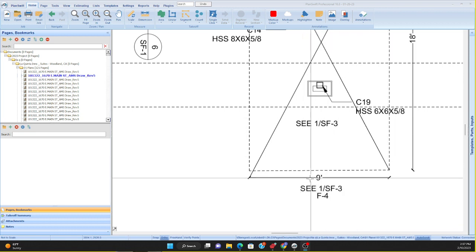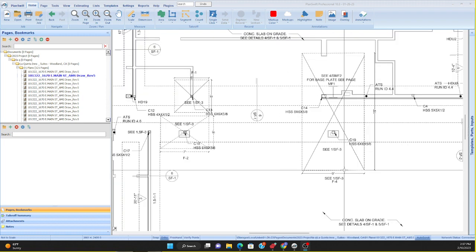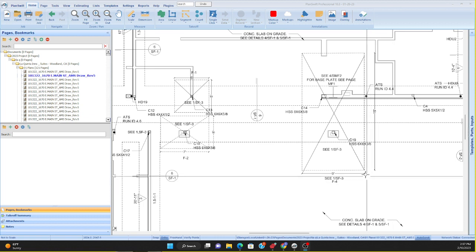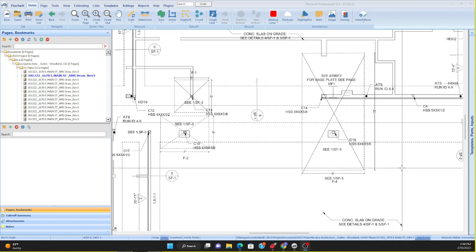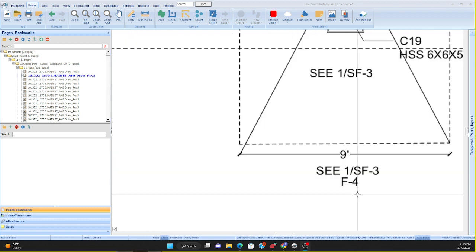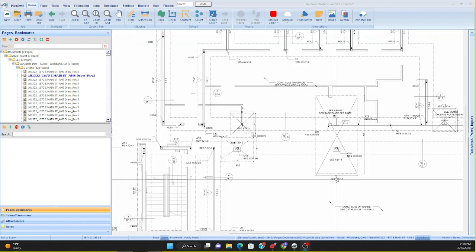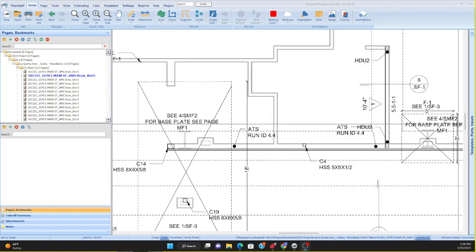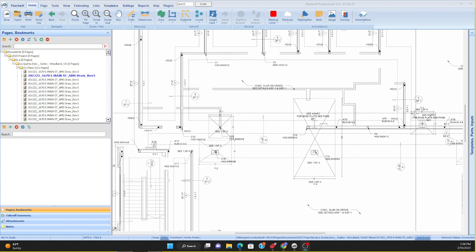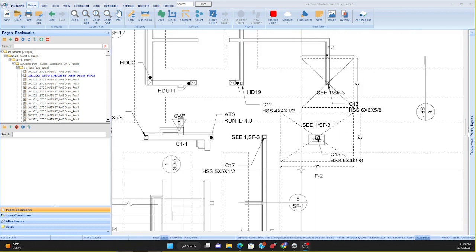And then this 9-foot opening, oh, is footing 4. Oh my goodness, that's a pretty big footing. 9, but wait, what? No way. C1 over SF-3, F4. No, there's no way. I guess so, there is a way. These are footings. These are huge footings. 7-foot by 5-foot footing with this on the interior.